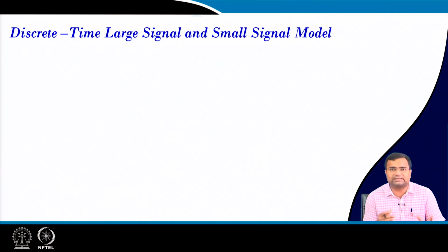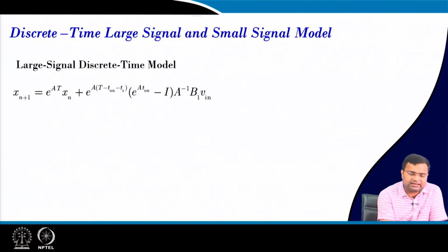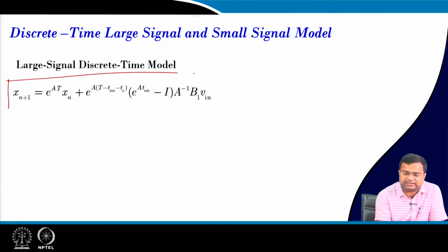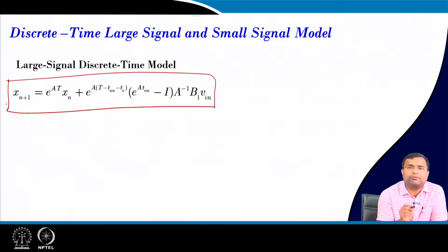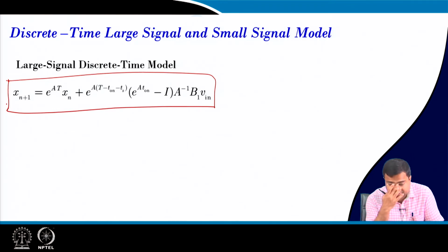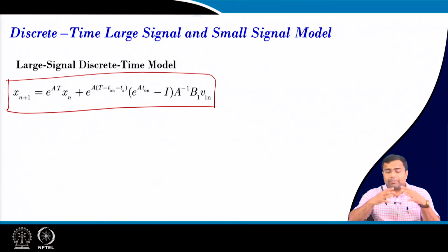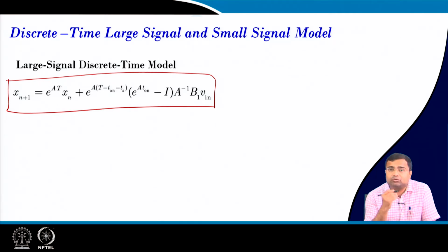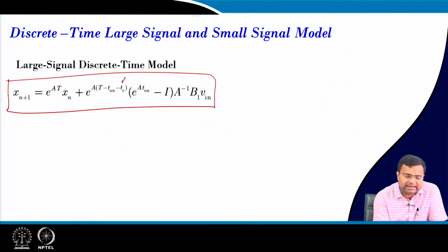And we have also discussed how to derive the discrete time large signal model, in lecture number 33, 34, as well as lecture number 38, about the large signal model, where for a buck converter under trailing edge modulation, interval 2 sampling, this is the delay, and this delay can accommodate the ADC conversion time, controller computation time, as well as the DPWM delay.